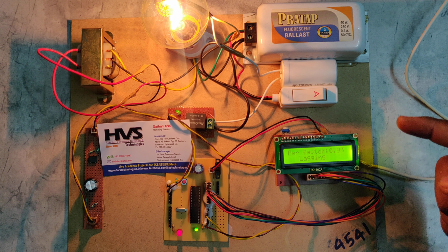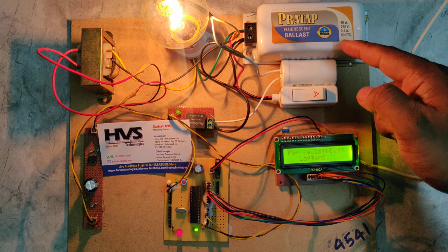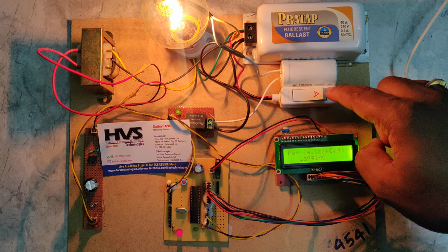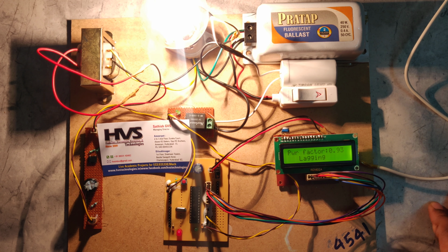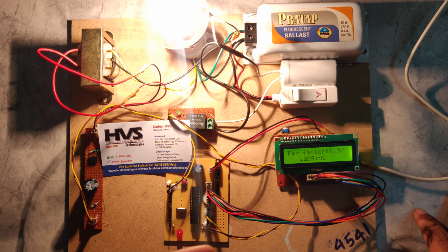Then if I isolate this inductor from the resistive load, the brightness will increase, and R plus C are in parallel, so the power factor has to lead. Let me check. It is starting the calculation, so it will take some time. Now we need to restart. Now see, it is coming to that, and the capacitor is still in parallel.